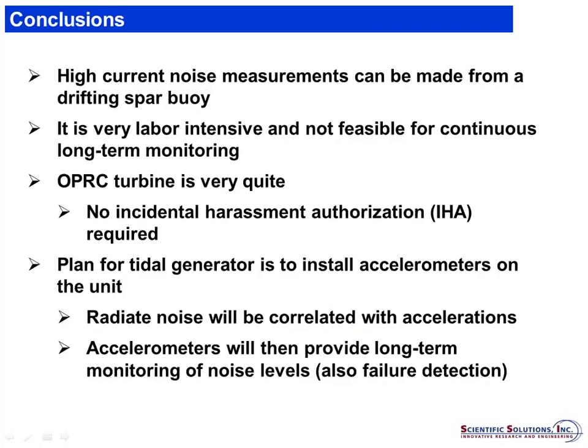The plan for the ORPC tidal generator is to install accelerometers on the unit, and we'll make some initial measurements where we correlate the signals from these accelerometers with the radiated noise. It's the accelerometers that will provide long-term monitoring to determine if the radiated noise levels have increased, but also for failure detection. And that's the end of my slides.